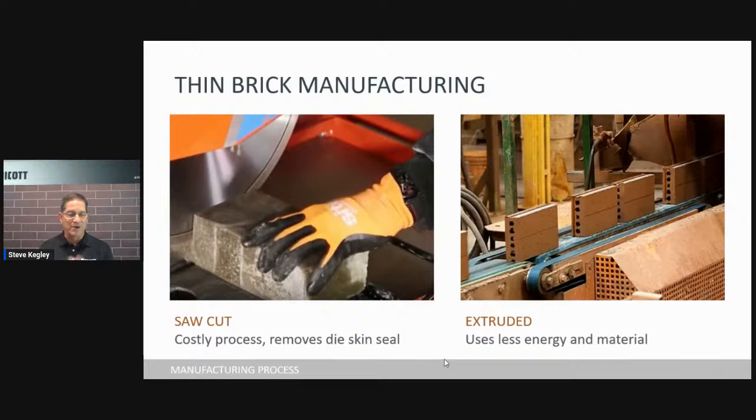clay. Now, I'm not going to get into ceramic engineering today because that's not what I do. But I can tell you I've talked to many ceramic engineers and asked them to explain this, and it is real. Okay. The other way, other than to take a face brick and saw cut a 1/2 inch off the front of it, is to extrude it as a thin brick or a tile.